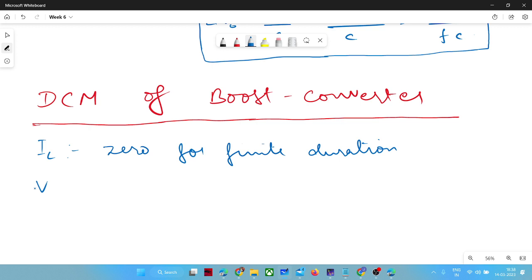It is very straightforward that if you increase the inductance, you will get CCM, a lower ripple in inductor current, and hence a lower ripple voltage. But inductance and capacitance make your circuit bulky. Generally, power electronics converters, particularly DC to DC converters, are not bulky. To get a compact design, you will have to play with certain other parameters. So you cannot directly call it a drawback. I hope I am able to clear your doubt.